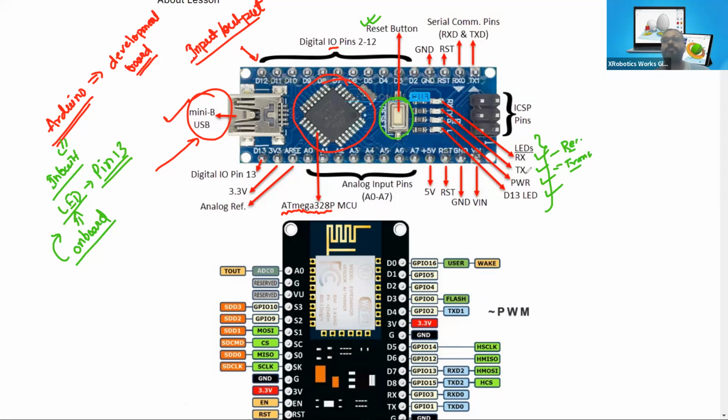And when the board is making a connection with the computer to provide us feedback or data output in the form of the serial print function, or the printf function as we have seen in different programming languages, the TX LED will glow. It only represents whether communication is happening between the devices or not. That's all. The power LED signifies whether the board is receiving power from the mini USB port or from other places.